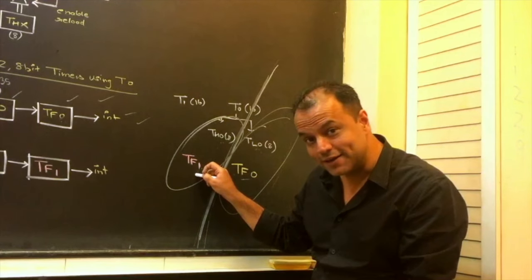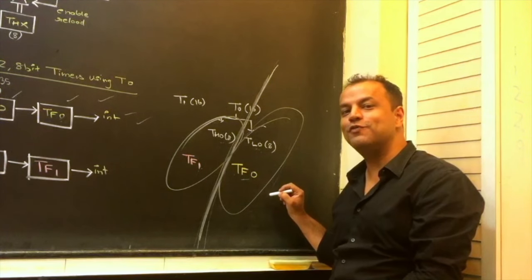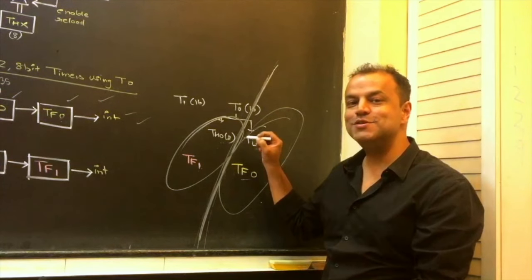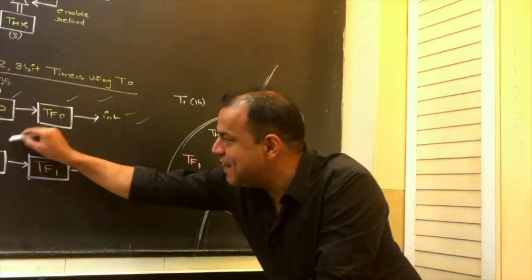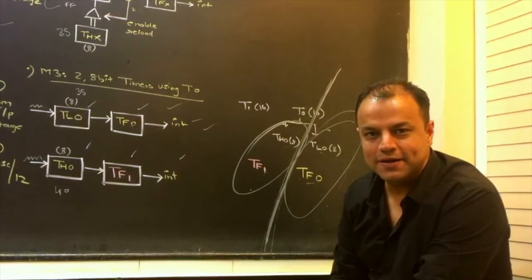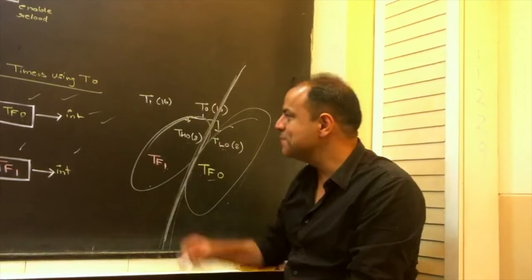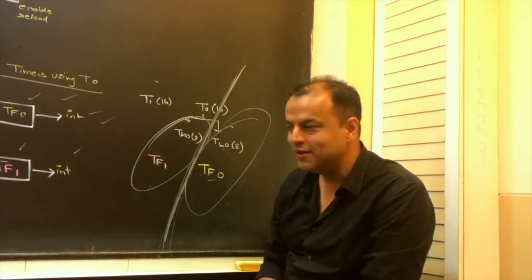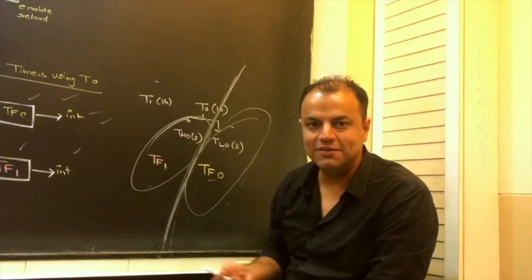Did you hear what I said? Timer 0 lower byte uses the overflow flag of timer 0. Timer 0 higher byte uses the overflow flag of timer 1 and has successfully become an independent 8-bit timer. So who lost in this bargain? Timer 1, poor thing. The problem was happening in timer 0, they used up the resources of timer 1. Timer 1 didn't even have a problem.